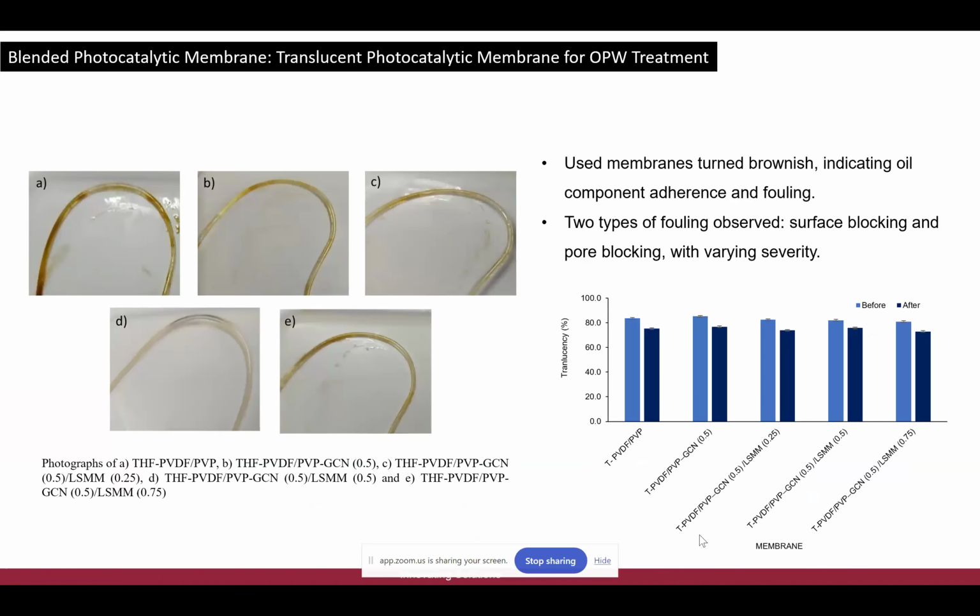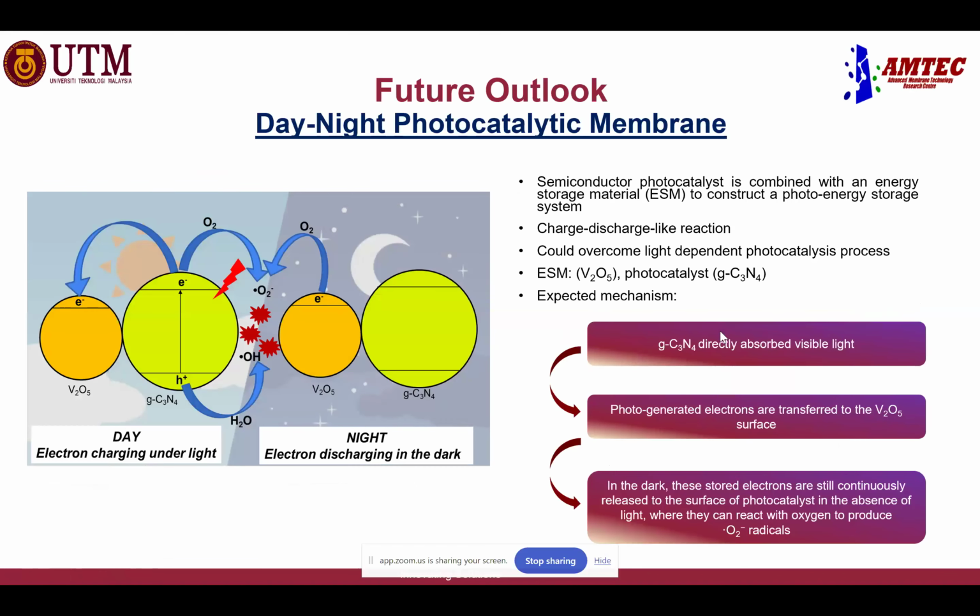We also observed our membrane after the test, and with the good formulation of the materials in the membrane, you can see very few oil particles on the membrane after the test. We also observed the translucency after the testing, and you can see the reduction of the translucency is very small, less than 10%. And for the future outlook, we are studying the day-night photocatalytic membrane, whereby the semiconductor photocatalyst